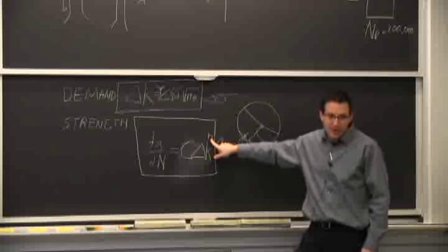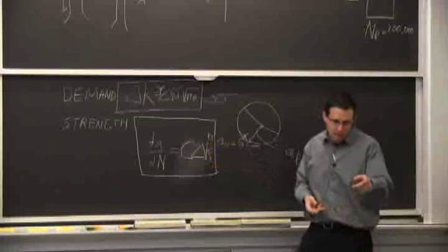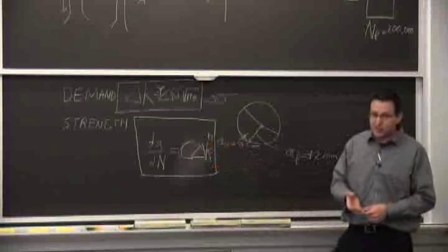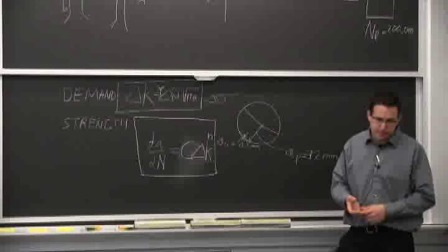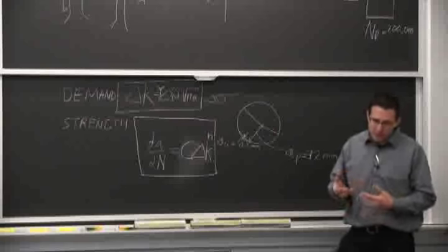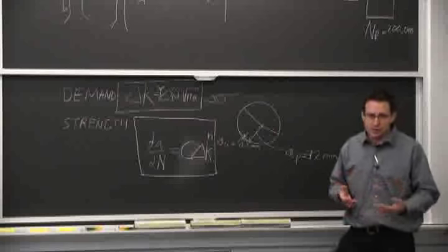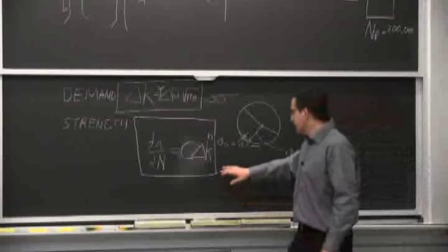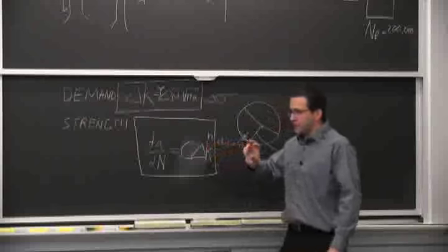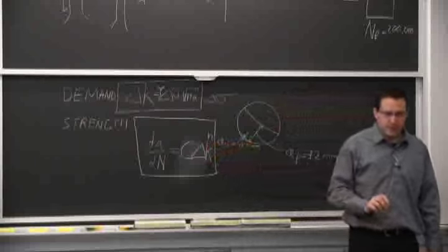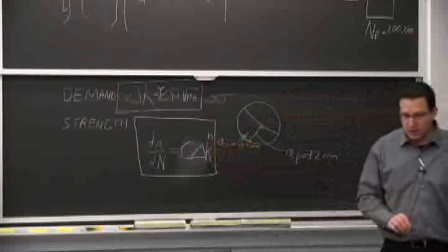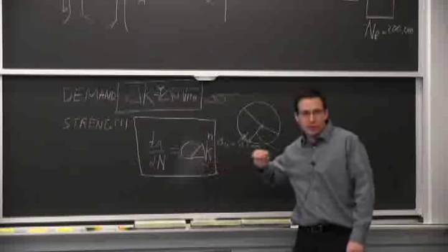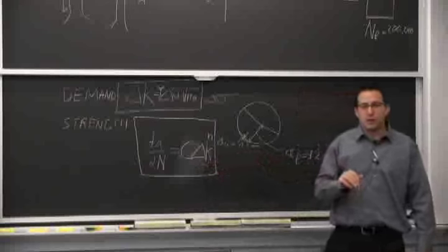But we need to have it for the right loading ratio, that's R, the right material, and sometimes even frequency or temperature, environmental conditions can play a role. So the equation is simple, but the thinking behind it is tricky. You have to make sure that the way these tests were done to give you these curves in the laboratory are close enough to what you're designing.